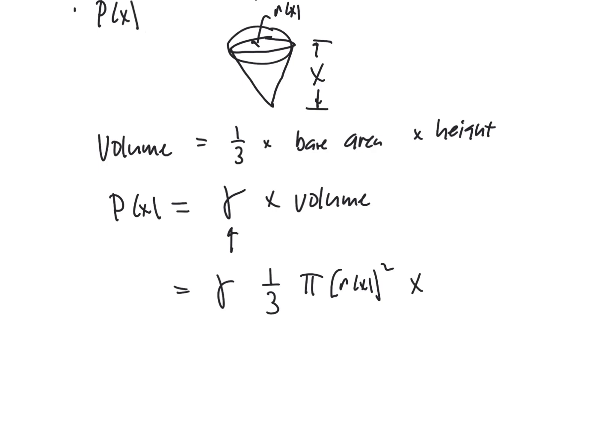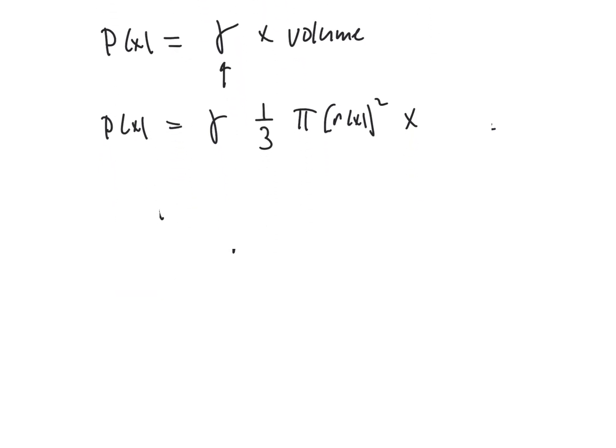So now we have it. We've got our P of x. We already had our area as a function of x. And we are ready to go then. We can set up our integral to evaluate that total displacement. So delta is equal to the integral from 0 to L of P over AE dx.